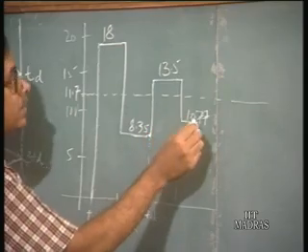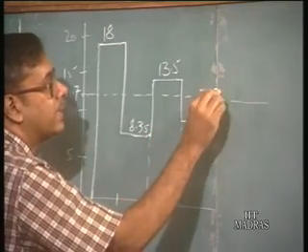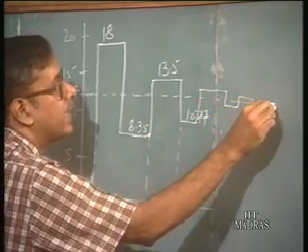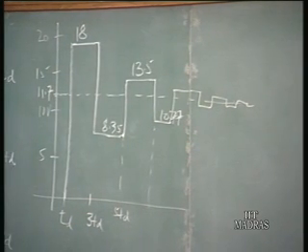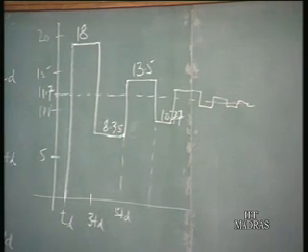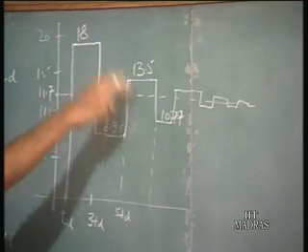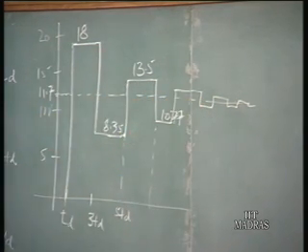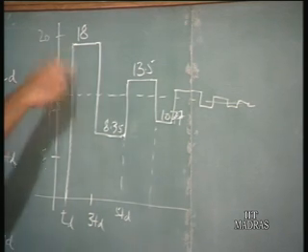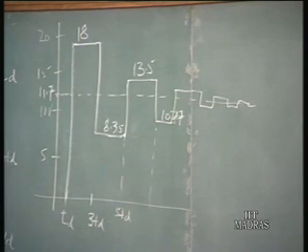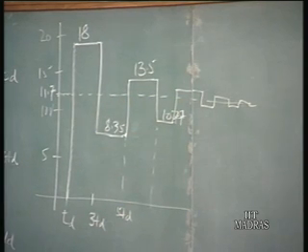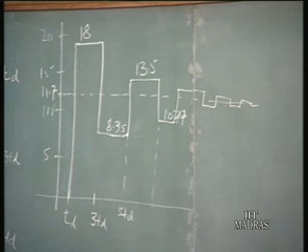Okay, so it will go up like this and then down, and finally it will settle down to this value of 11.7 volts, which is the one we expect, the voltage we expect if the transmission line is to be neglected. So in actual practice, we will have a waveform which is very much distorted. And it takes some time to settle down to the final value. So this is the effect of the transmission line on the signal.